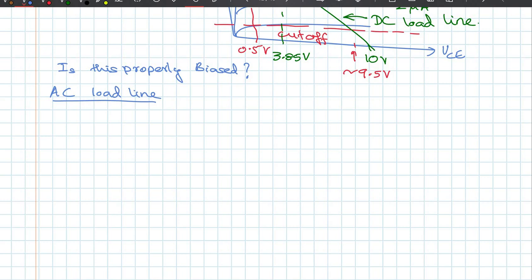The impedance posed by the capacitor should be way smaller than your resistance value. Typically a rule of thumb is about 1/10 or less, so that when the current divides, less than 1/10 of the current actually goes to the emitter resistor.